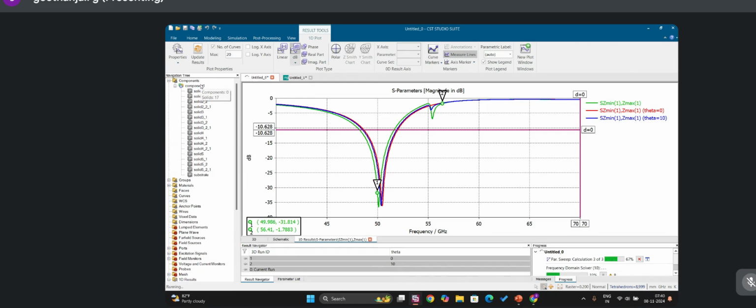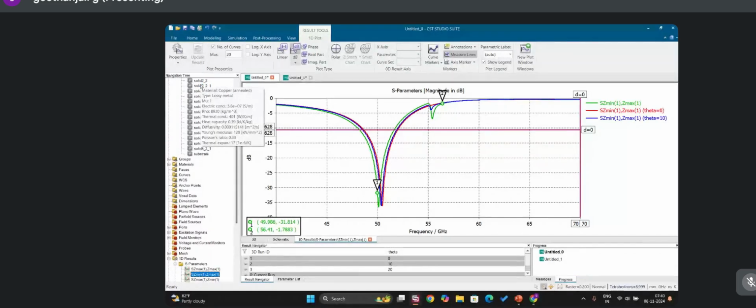So if the FSS is designed at very low frequency, like 0.5 to 1.5 gigahertz, the accuracy of the angular stability will be very high, like 85 degrees, 75 degrees, as I said in yesterday's session.